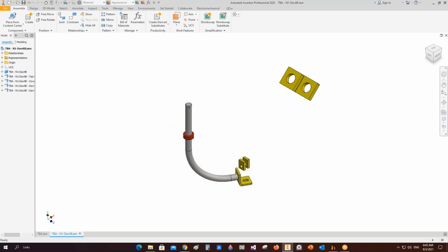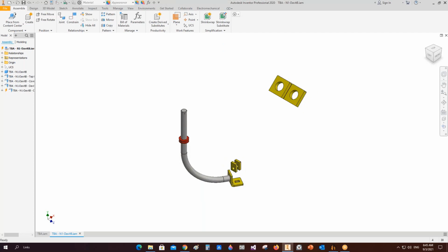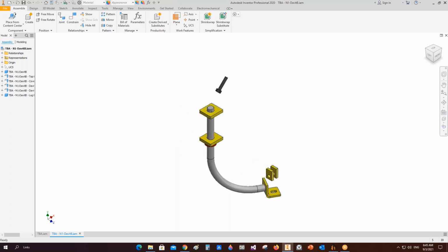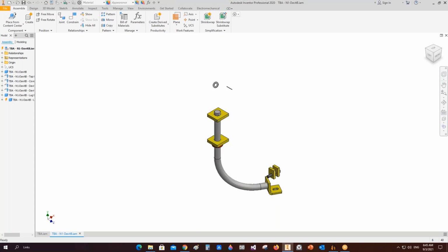As you can see, it takes some time, but it's not a huge time. It's just maybe 1 minute. But if you compare it with the Davit as one element, you will not get a bill of material for it. You can use that in case you have a larger model and you would like to make it faster a little bit. You can make this Davit in detail for one nozzle only, and keep the other Davits as one part.